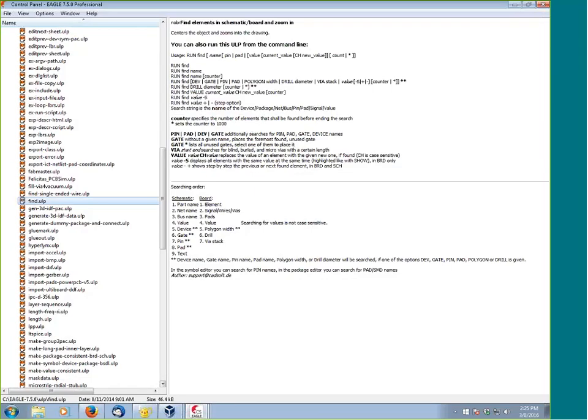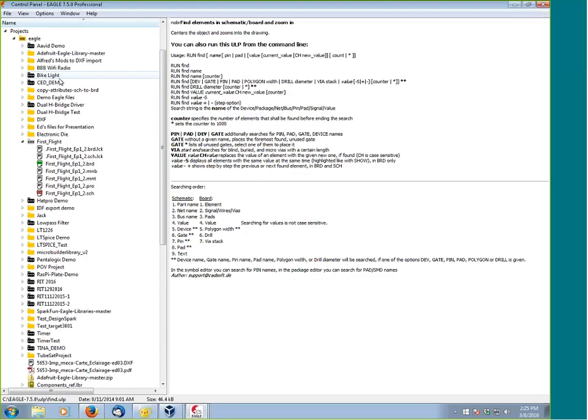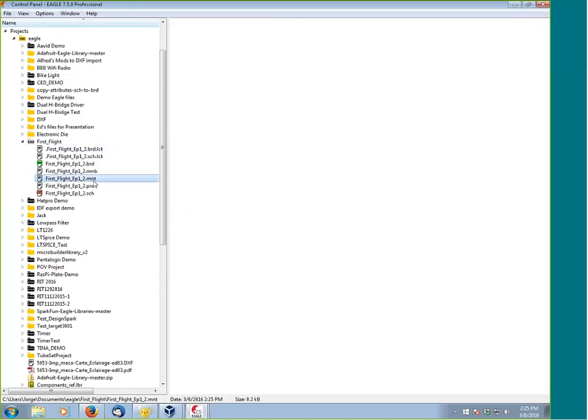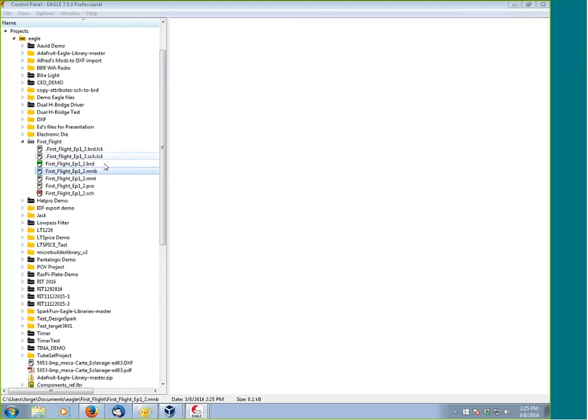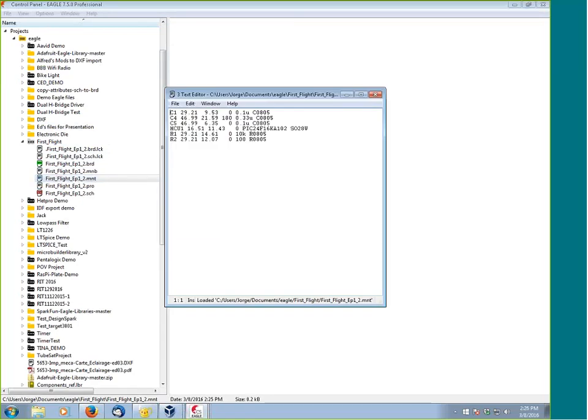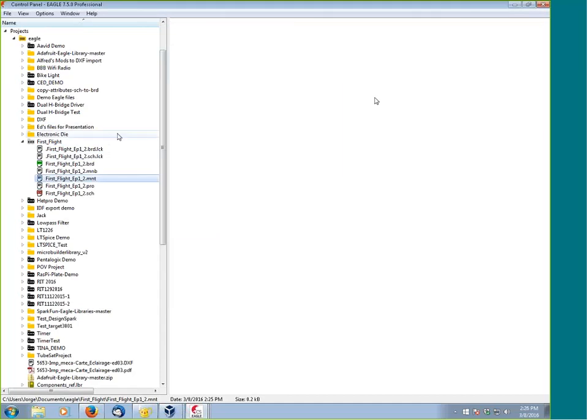And so you guys have an idea of what these files look like. They're actually very simple files. They're purely text files. So we go over here to Projects, and you'll see that now we have an MNB and an MNT file. MNT, mount top, MNB, mount bottom. So if I open up the bottom, which is the one that's going to have less data, you guys will see it's pretty simple. We have the reference designator, X location, Y location, its rotation, value, and package type. Okay, pretty simple. Because it's an MNB file, they know this is for the bottom. MNT works pretty much the same way. Okay? So very simple files, but usually this is enough for the manufacturer to get the data they need in order to be able to assemble your board.